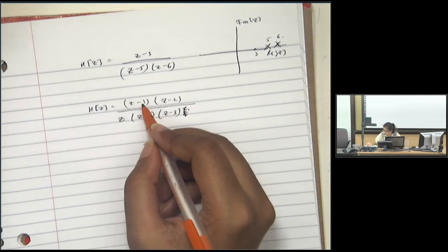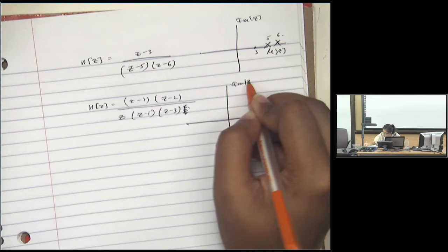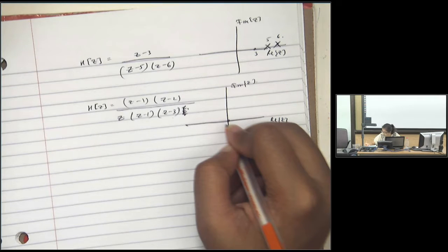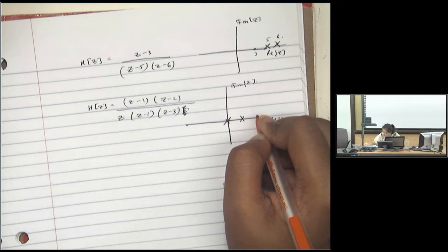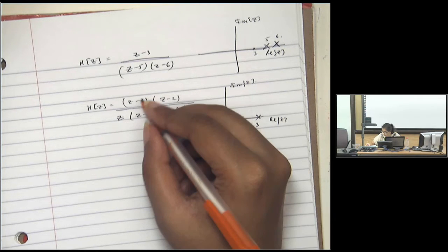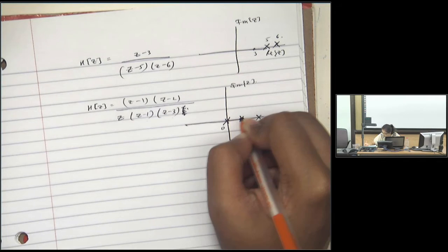So with the real z and imaginary z axis, this is the origin. We have poles at 0, 1 and 3. And zeros are at 1 and 2. So the zero at 1 will cancel the pole at 1. You'll have a pole and zero here as well, so actually you don't have anything, right?